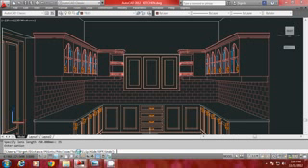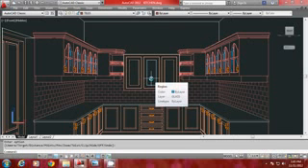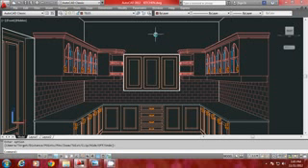Or else you can also go for zoom option and you can give a higher value for focal length and you will get a zoom view, or it will be having the same effect of putting a zoom lens in the camera. So this is how you generate a single point perspective. Now you can see that we have only a single vanishing point. So I will explain the method once more.